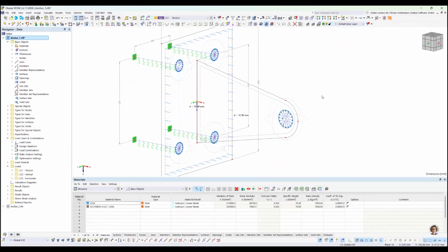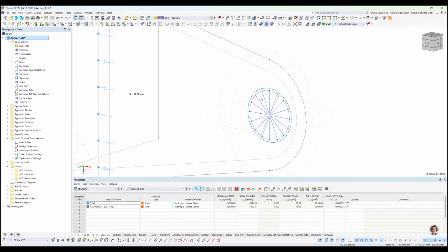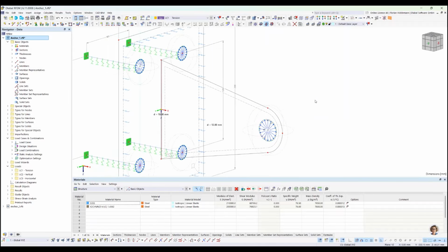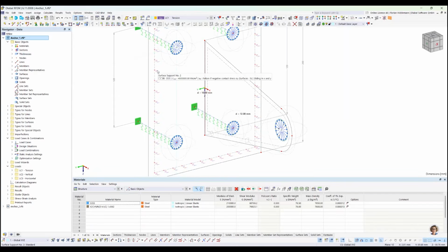I would like to show you the basic initialization, the setup for the add-on optimization, how it works together with the stress-strain analysis. We do some design setup here as well. And I would like to point out some nice details in this model. For example, how to properly model some screw connections, or to get a more realistic result by applying the loads on some holes like this, and have a backend plate with a non-linear support for the surface.